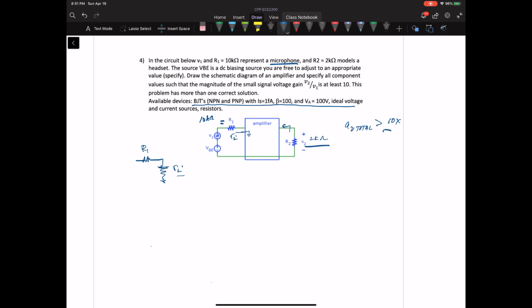So given that we do not have limitations, and we're given this high source resistance, I know we want something with high input resistance. And of the amp configurations, we only know 2 at this point. For the common emitter amp, the input resistance is just r sub pi.